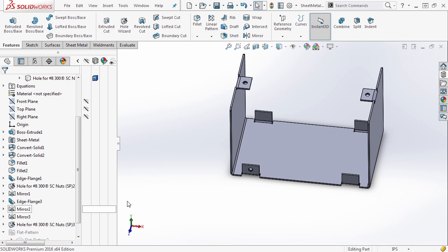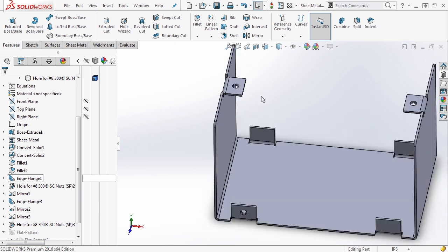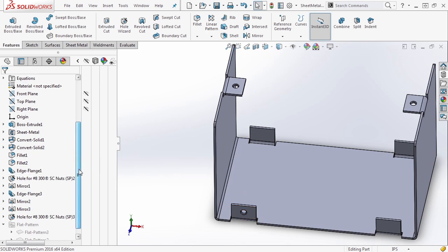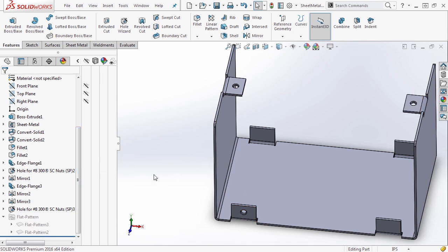For instance, if I punched in the manual value 0.08 to cut that hole through my part, and let's say that somewhere down the line I decided to change the thickness to be 0.1, everything else would update, the flanges would update, but the manual offset of this flange downward and this flange inward would not update. So we really need to understand that when we're making these parametric files, we need to know exactly what is going to update and what's not going to update.